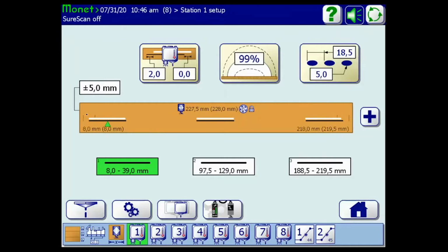You can see the little dotted lines around the start of the first event. Those same dotted lines are centered around the end of the last programmed event. You guys can see that okay. So basically this is my criteria for glue detection, what we deem as acceptable. This is my start tolerance. It needs to see my glue start within this little window here. And most end users depict the gap between these little dotted lines as 5 millimeters.